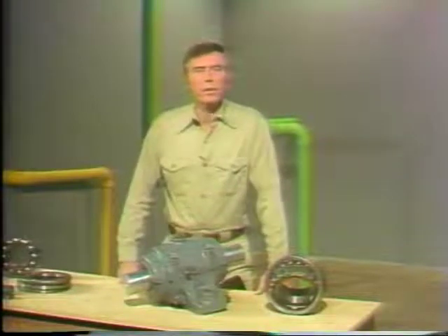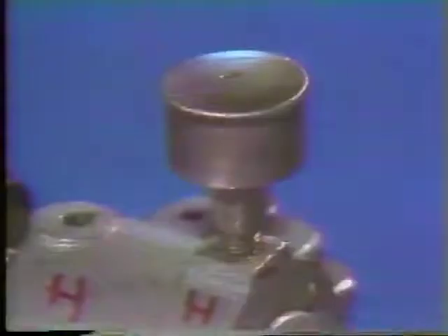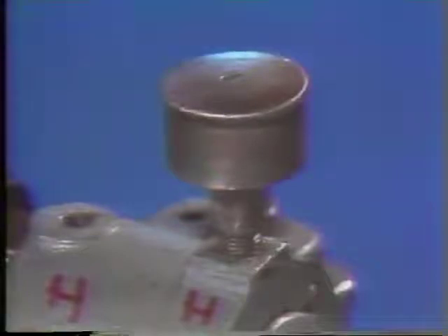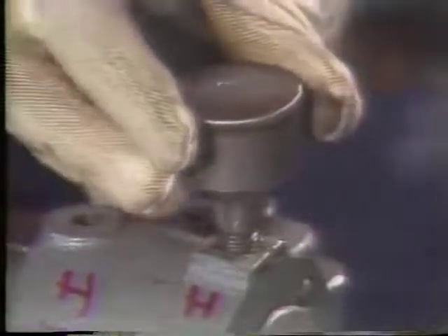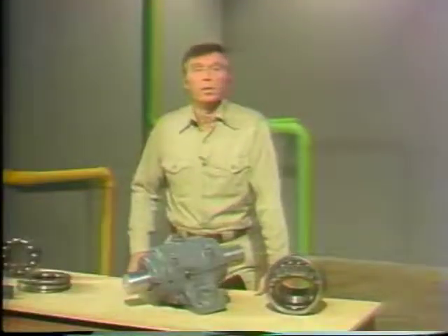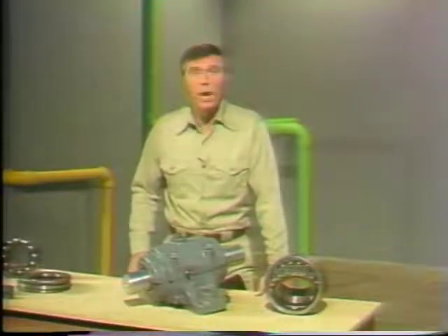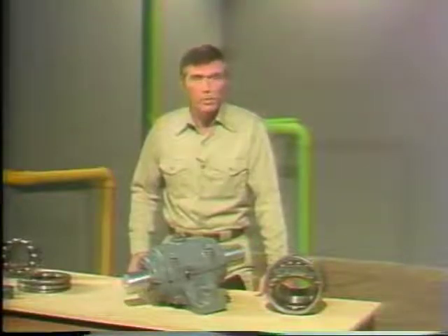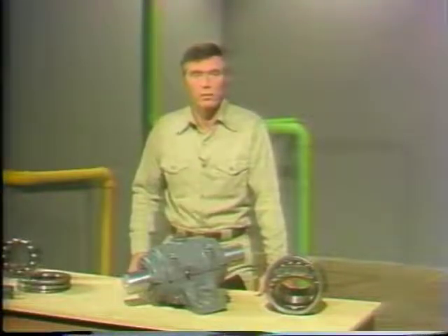Another method of greasing a bearing is to use a grease cup. A grease cup is a container with grease in it that is mounted right on the housing. To force grease into the bearing, you turn the top of the cup. Usually, 1 to 2 turns is sufficient to grease the bearings. Again, your plant may have specific guidelines concerning how much and how often a grease cup should be operated, so ask your supervisor about them before you start. Also, make sure there is enough grease in the cup before you begin. If it's nearly empty, refill it with the right type of grease.